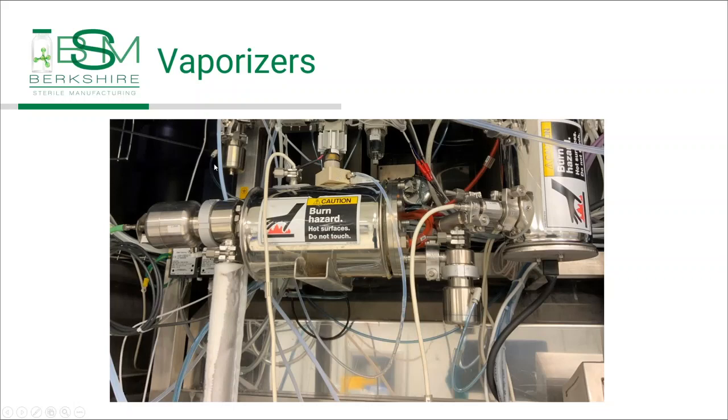You can see, follow the line back, which is up over here. That pump then pumps into the vaporizer, which again is just a heated plate on the bottom that evaporates the hydrogen peroxide and water. And then that goes into the chamber through this stainless steel line here, which is insulated. It's a very short line into the chamber. This is a multi-chamber system, and each chamber has its own vaporizer on it.